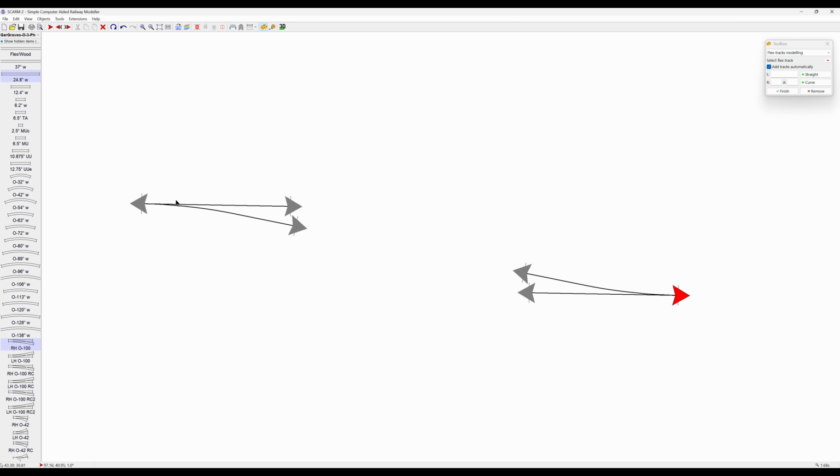But SCARM has to figure out where exactly to place your objects, and it's probably got a calculation to get it close to a snap point, and you're not going to land it on every snap point. I don't know of a setting in SCARM to get you to snap to a node or even down to a pixel. So it gets it close, and so when you get things not quite lining up, no matter how you move it, it's probably due to the precision. And the 0.079 is a SCARM default.